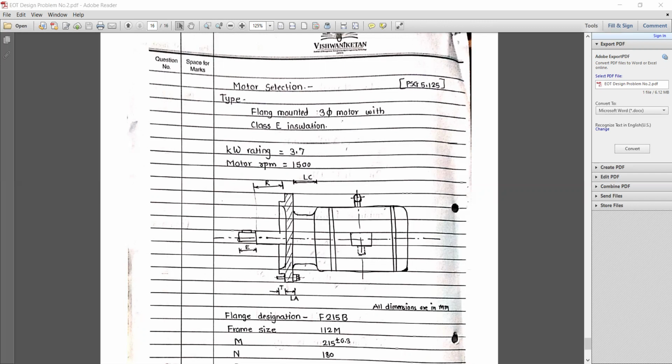So our requirement is 2.23 kilowatt. Now if you look, there are 2.2 and 3.7. The value is in between. If you think your 2.2 motor is able to sustain it, I still prefer you don't go for 2.2, go for 3.7, so that if a sudden load or any additional load occurs, your motor will be able to sustain that load also.